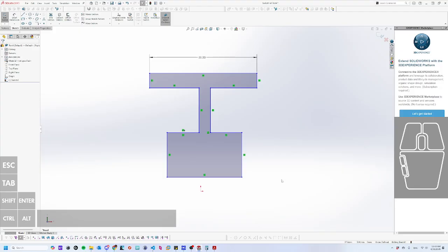So I'm just going to keep dimensioning. If I hold down right click, and you can see it highlighted, and I move my mouse a little bit, it brings up this wheel. If I move my mouse upwards even more, it brings up the smart dimensioning tool represented by that symbol, the two arrows with the two lines. If I bring it leftwards, it lets me select the line tool relatively quickly. If I bring it rightwards, it selects the circle tool, and if I bring it downwards, it brings the rectangle tool. So since I'm dimensioning right now, I'm holding right click and I'm dragging upwards, and the symbol appears next to my mouse cursor to show that I'm in the dimensioning tool right now.